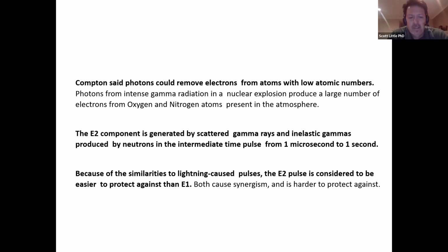And then these are okay. They fit within the spectrum of lightning pulses. So you're able to use lightning surge protection for those. You couldn't do it with the E1, it was just too fast, but it'll work for the E2.